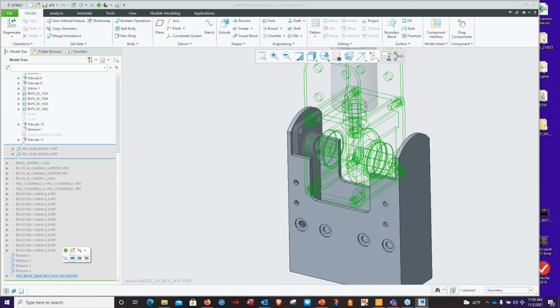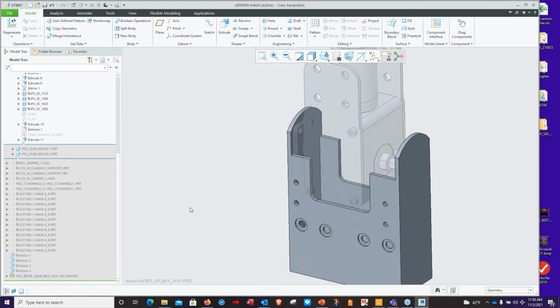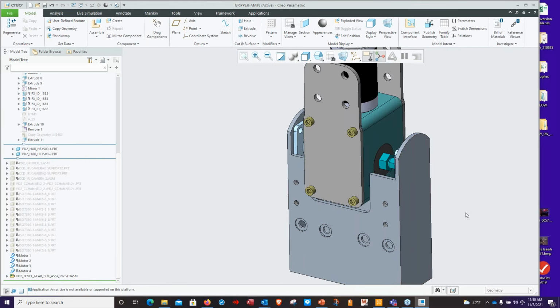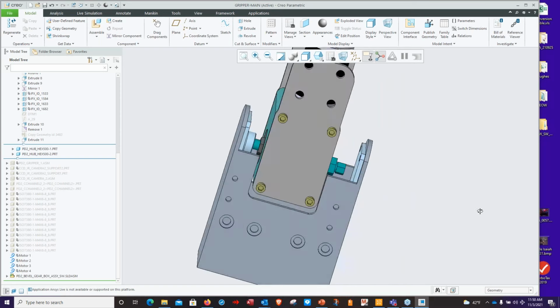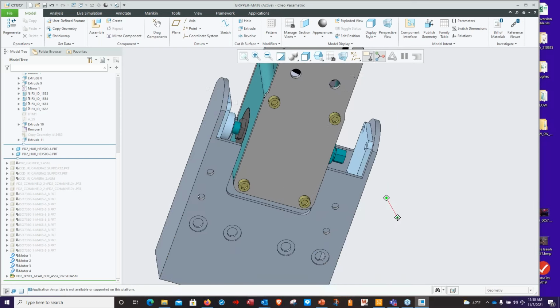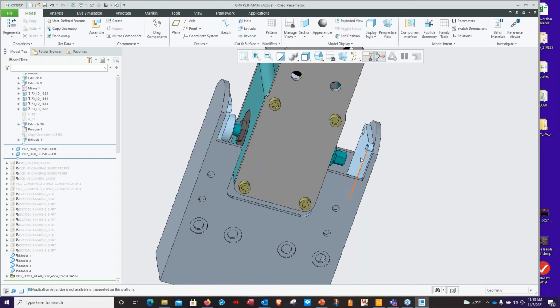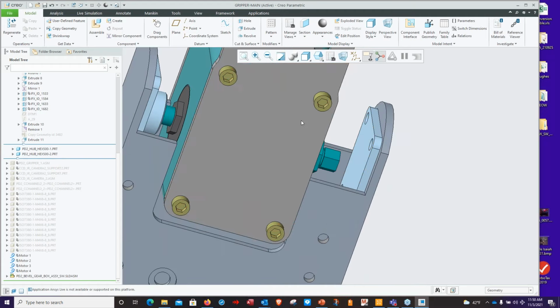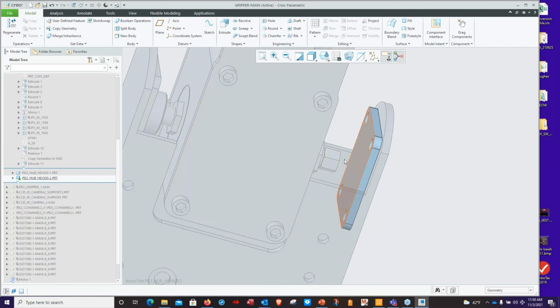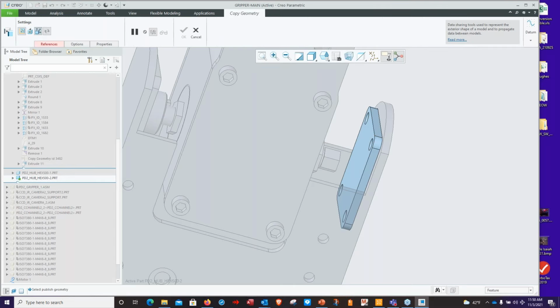We can resume and see our SolidWorks, and we're going to now go back and restore. So we're getting back into the assembly, activating the whole assembly. So now we can see that cut was implemented in here. Oh, we see we've got another change. And now we received this, we have to make a change on this. To go through the same process, let's select this part, activate. We need to create a receiving boss, copy geometry, go through the same processes.